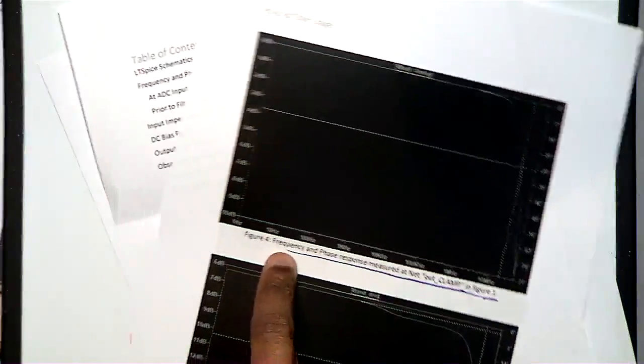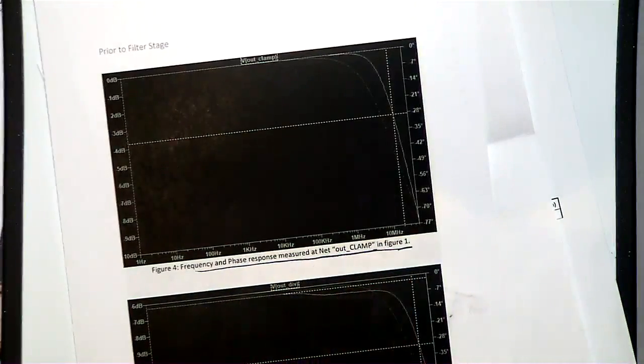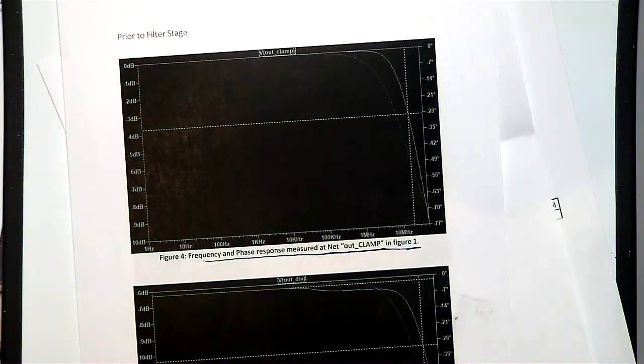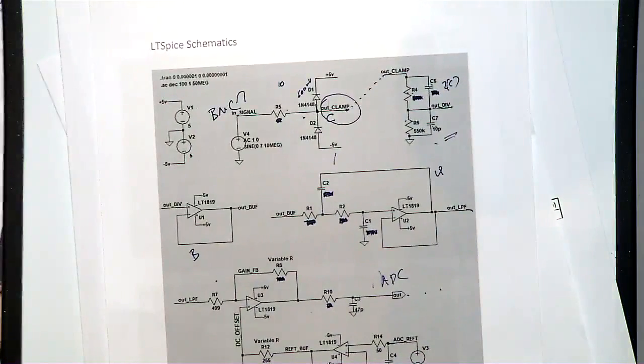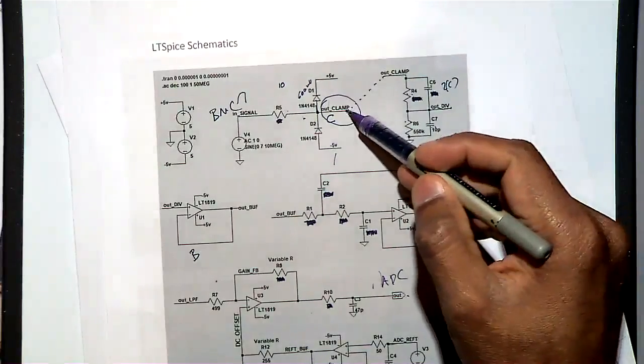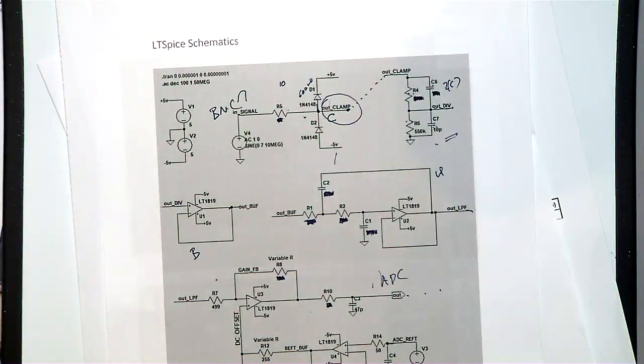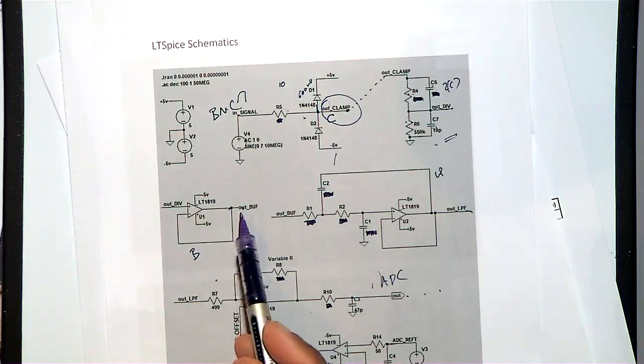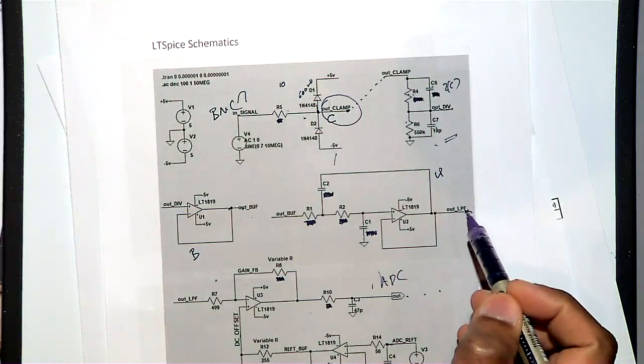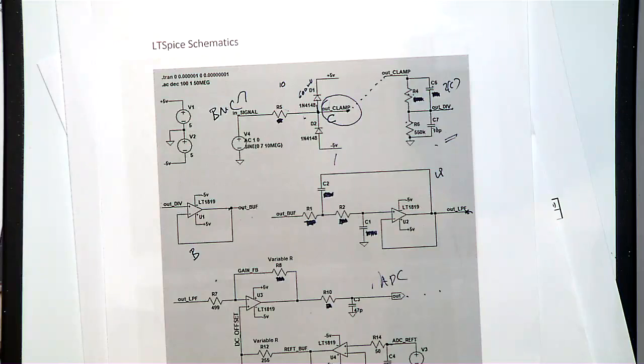For the simulation report, there is no confusion, because you don't have to worry about this heading. We will tell you exactly where to measure, so that in LTspice you put the probe there to get the measurement and then plot it. Impedance should be at the input. For example, maybe this year we will say measure at this point, maybe measure at the buffer output. Then it is easy. You put the probe in LTspice somewhere here, at this point, and measure it. Maybe you definitely need to measure at the filter output, because only then will you be plotting the filter characteristics.